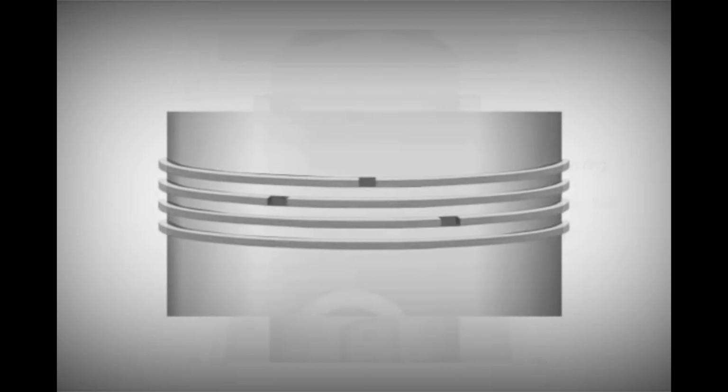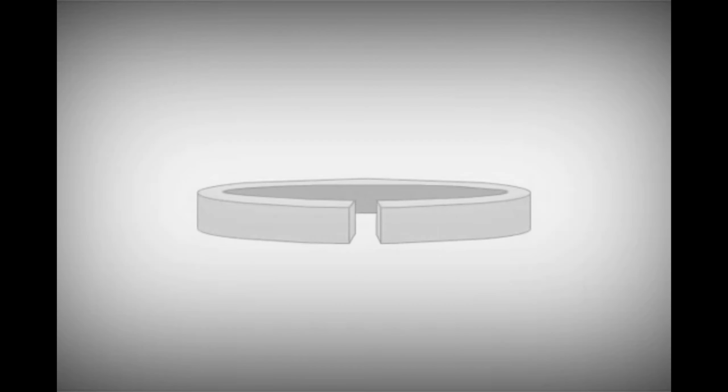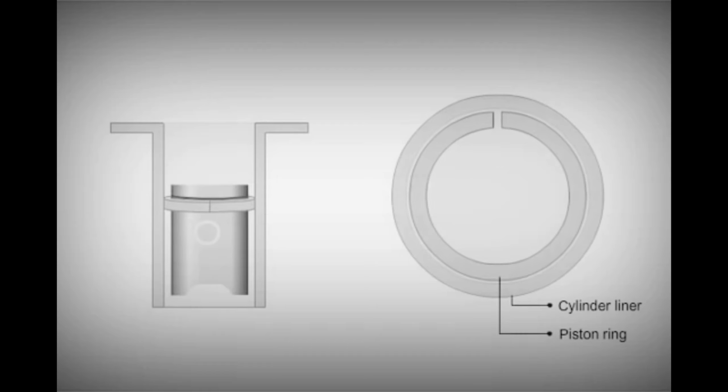Butt clearance is also known as ring end clearance or gap clearance. It is the distance between the connecting faces of the piston ring. This clearance should be within the limits specified by the engine manufacturer. The ring expands when the engine is hot. If the clearance is less than the minimum limit, the ends touch due to this thermal expansion. The ring expands against the liner. This increases the friction, resulting in breakage of the ring and seizure of the piston.